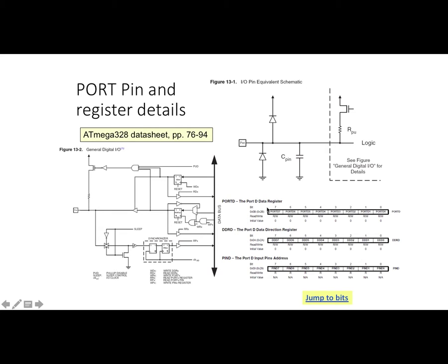And so now you can write all the bits all at once to the data direction register and then output data to port D. And that's kind of nice. The way things are set up here is we have tri-state logic and latches going in both directions. So we can have a latched register write, and a data direction register is really nothing more than a bunch of D flip-flops. And those D flip-flops can essentially serve as 1 bit of RAM each.